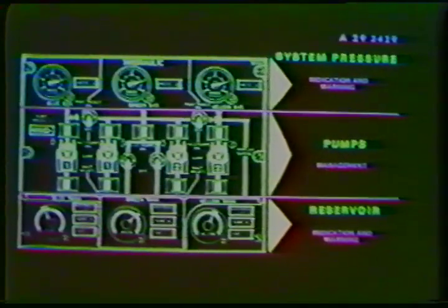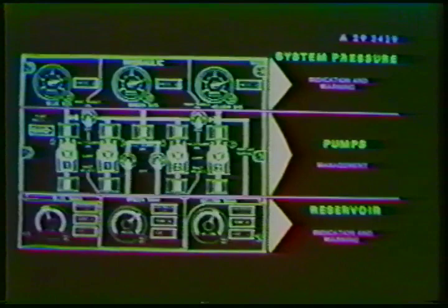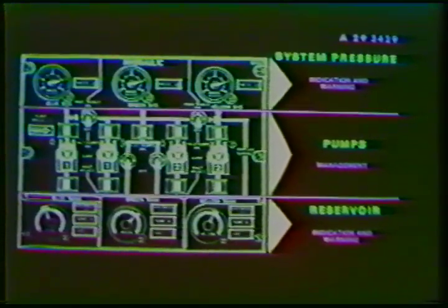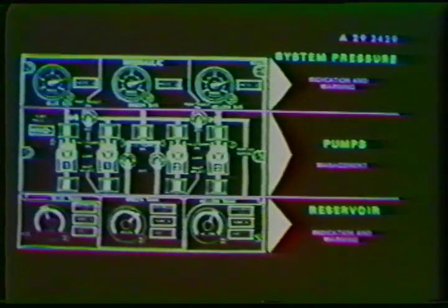The hydraulic control module is divided vertically into 3 sections to represent visually the 3 systems, which are, from left to right, blue, green, and yellow. Moreover, proceeding from the bottom of the module to the top, the physical arrangement of the controls and indicators displays logically the flow of hydraulic fluid from the tanks to the pumps and then to the pressurized systems.